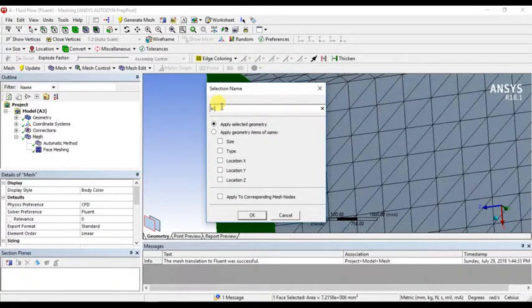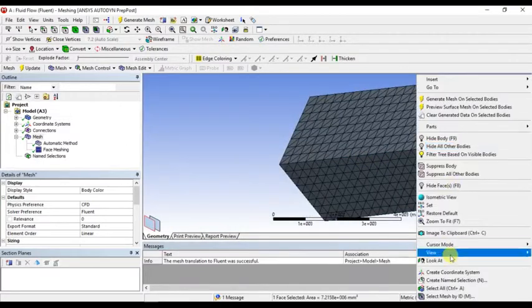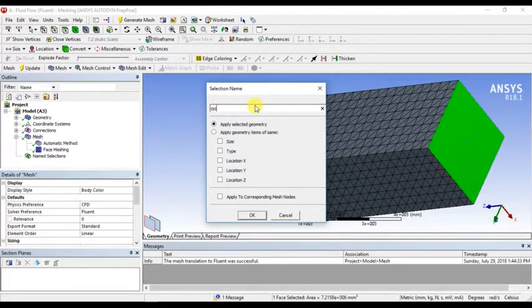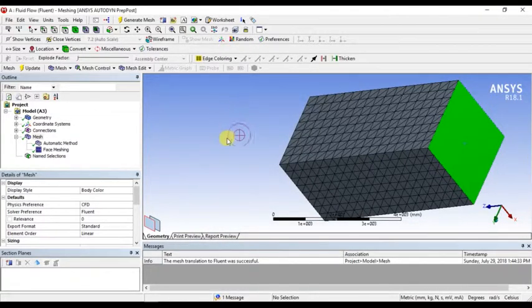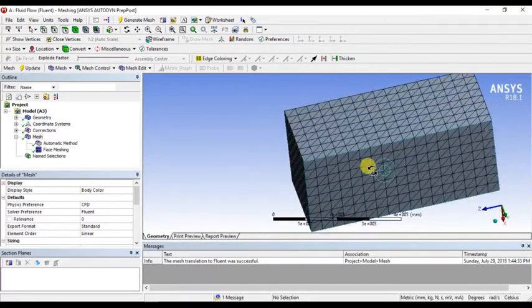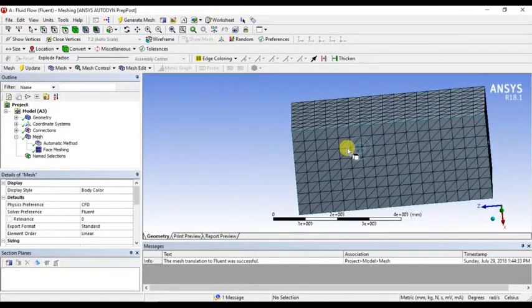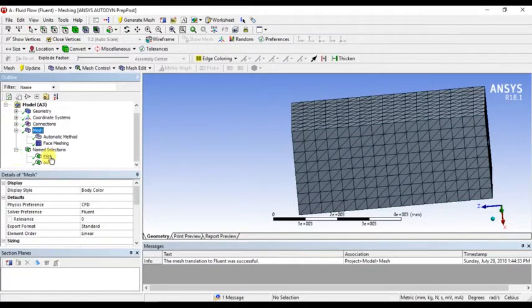Inlet. This will be outlet. In the 2D analysis, we have to give the boundary conditions and define them as a wall, but in 3D analysis we don't define walls because it automatically generates the connecting face between the rotating fan and the wall condition. So from here I will be updating my meshing for the further analysis. Now the mesh is successfully updated.